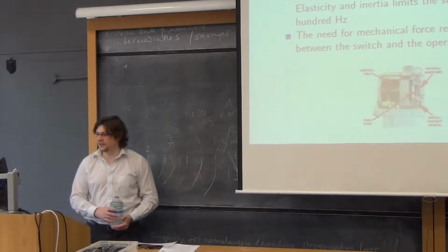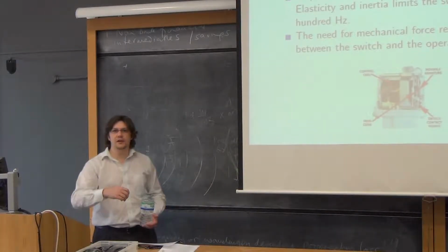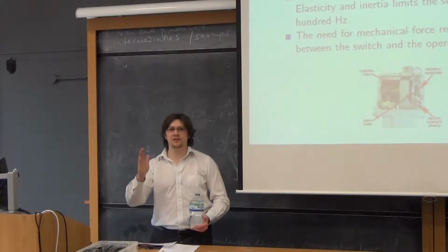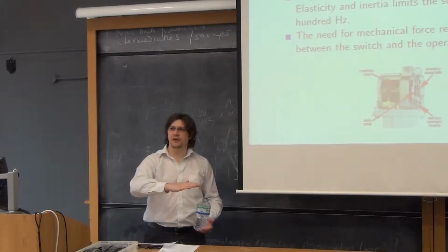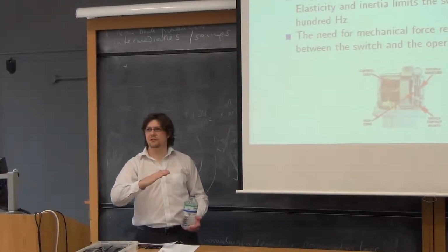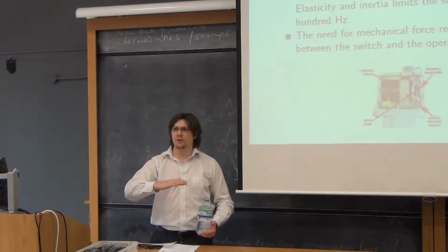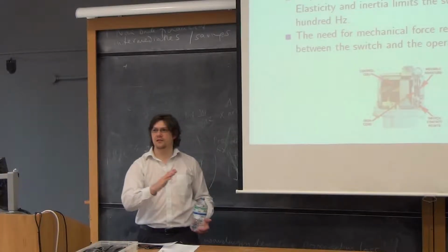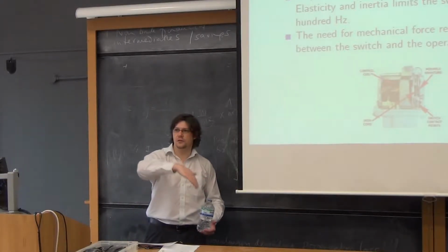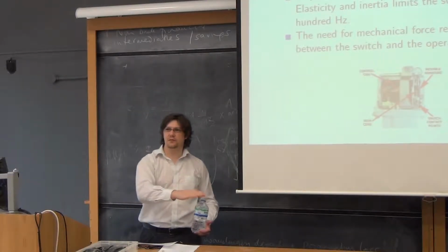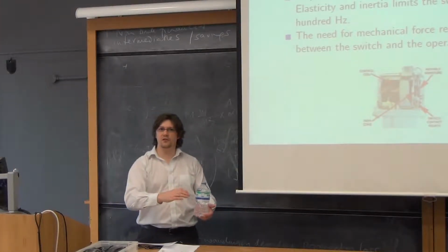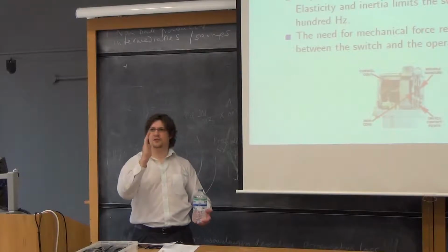They've got elasticity and inertia. That's to say, when you flick the switch, you're pushing a little ball bearing across inside, and that's making an armature move down. And the armature, even though it's metal, is quite thin usually. As you push it down, it will deform like that, and then it touches down. The same goes for when you pull away. The current wants to keep flowing, so there'll be a little force on the point where the contact is that you're trying to break, so there'll be a deformation like that.